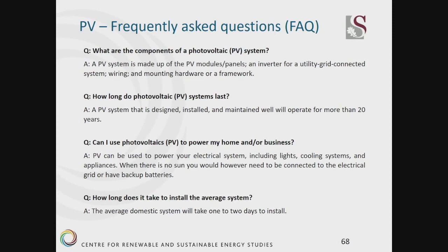Our utility scale PV installations have signed contracts for 20 years. PV panels are warranted for 20 to 25 years. Just take care that inverters will not have a warranty for 20 or 25 years and typically have a warranty for only 1 year. You could buy extra extended warranties on inverters, but this will also cost more. So make sure when you compare inverters that you actually do compare apples with apples.